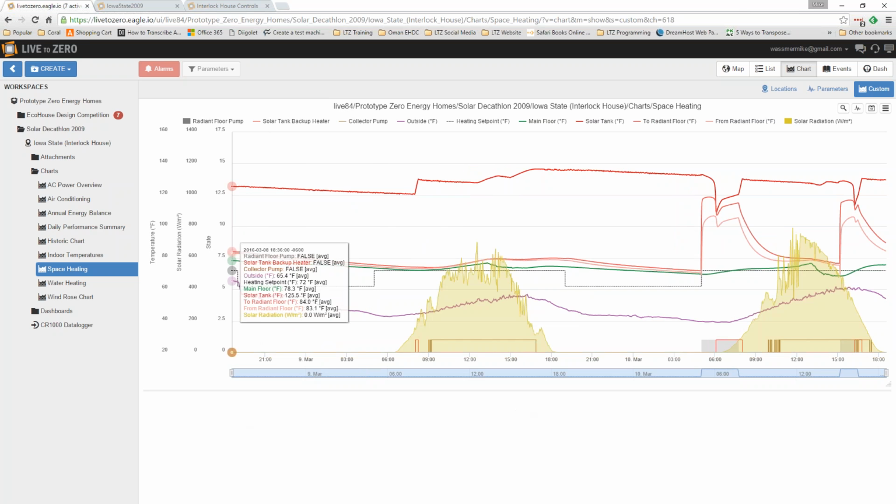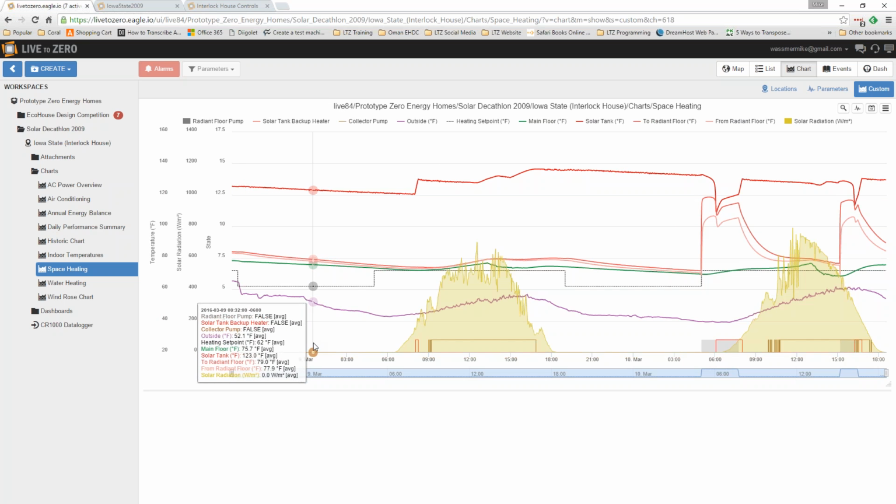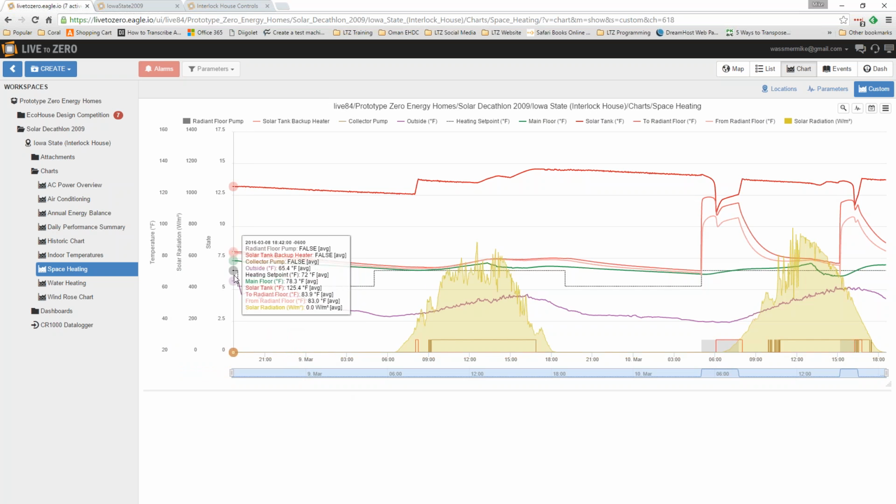So yeah, you could see outdoor temperature 65 on the previous day. The building was not occupied that day, which means that the occupants never overheated and never opened the windows. So the building was trapping all the heat that it collected all day long, and the temperature got really warm inside. So you can see here right at the edge of the chart, 78.